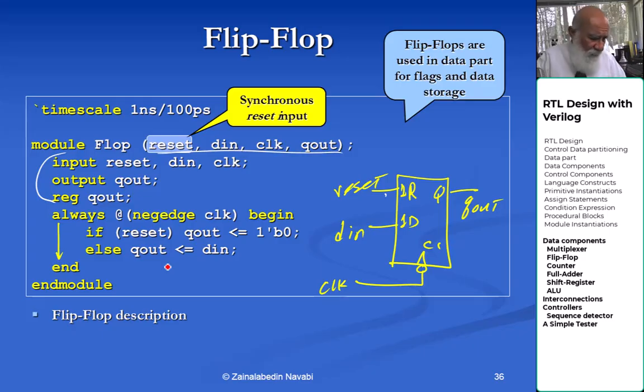And therefore this becomes a flip-flop with active high reset, and this is a synchronous reset. That means reset is only looked at during the edge of the clock.